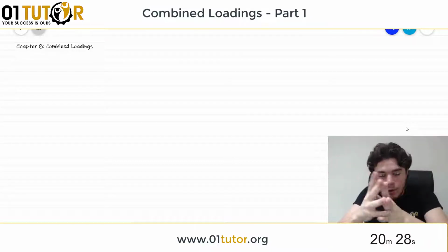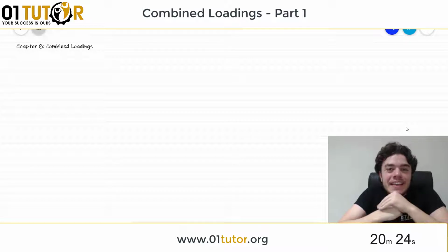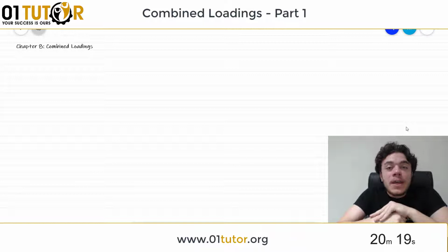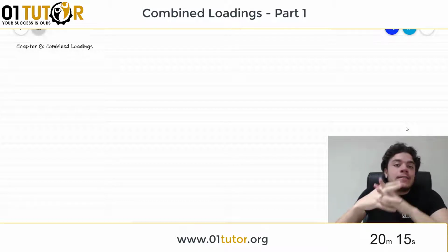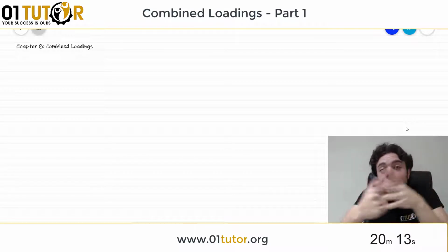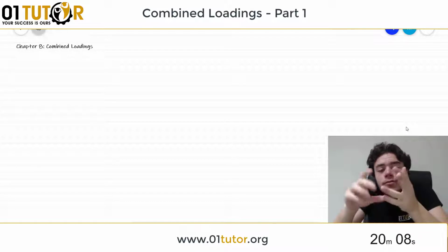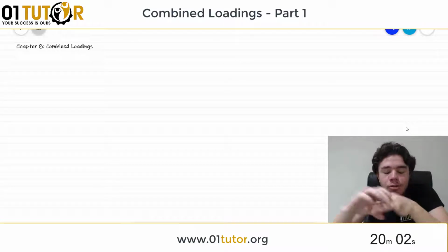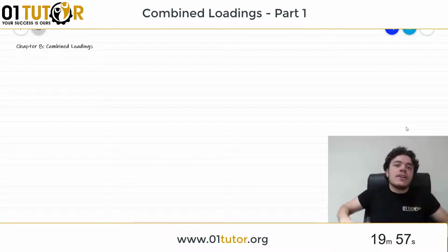Welcome to the chapter where we will be combining everything we did in the second part of the course and even in the first part of the course. We will be dealing in this chapter with cross-sections that are subjected not only to double bending but also to torsional moments, shear forces in both directions, and concentrated normal forces. So we're going to be dealing with sections with more than one loading acting on the section.